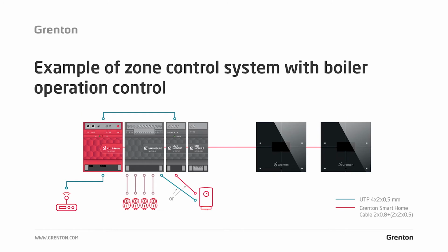As you remember from the previous training videos, the system presented in the previous diagram can be further expanded with boiler control. Earlier, we controlled the receivers, i.e. the heat supplied directly to the radiators or the floor heating loop. You can also connect a boiler controller to such a system, so if you wanted the boiler to turn off when all heaters are closed, you must connect it to the system. It can be done in 2 ways.